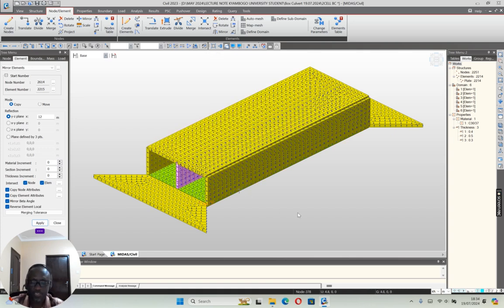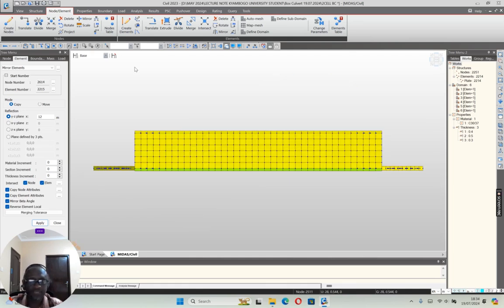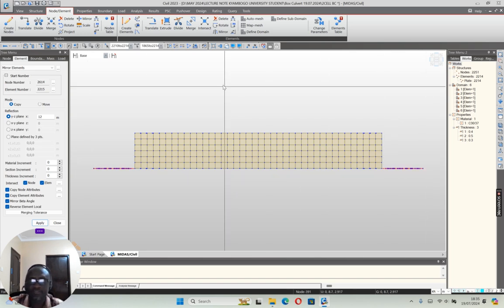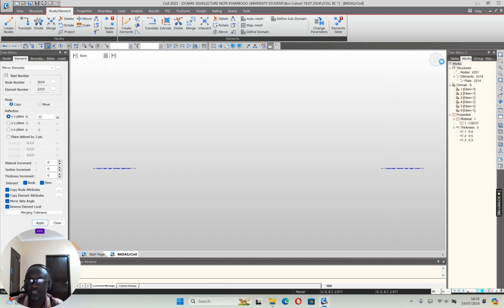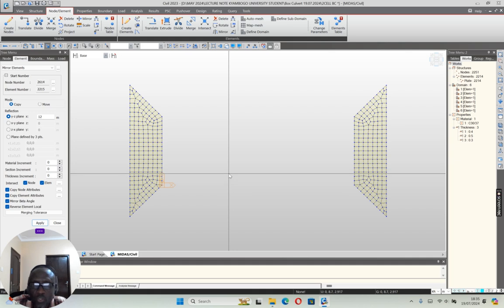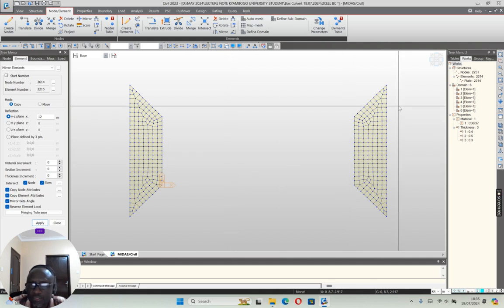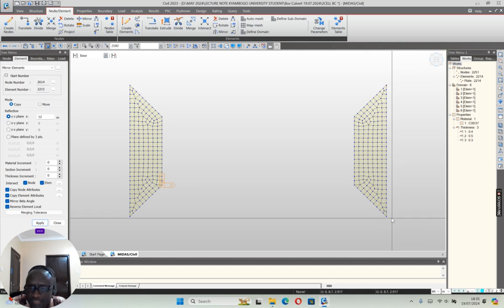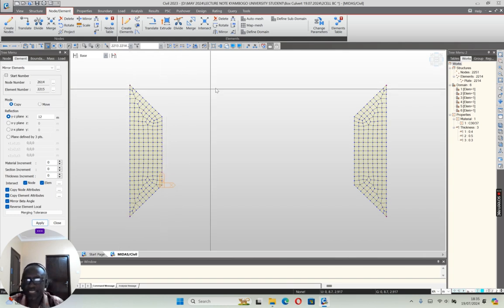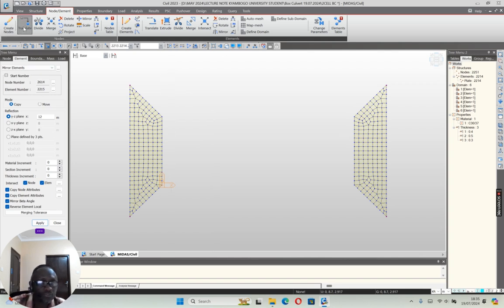Now we need the wing wall. How do we do the wing wall? I just have to make sure I also activate the apron, and in the apron, I just need to make sure the extent of the apron, I raise it by a meter. This one I raise it by a meter. So I just go to translate.